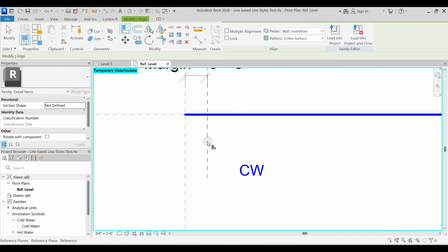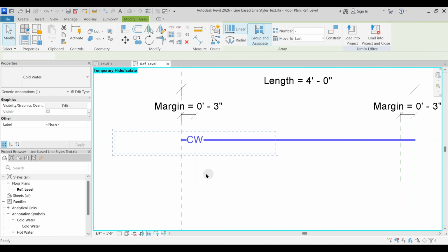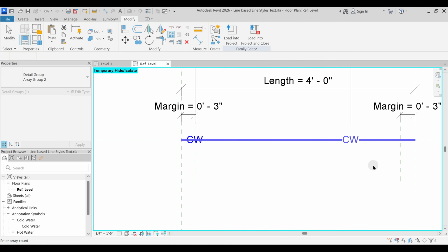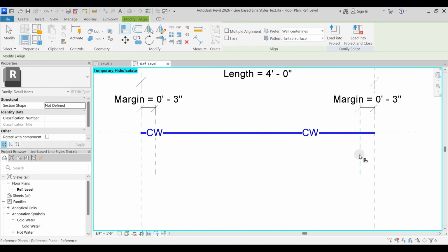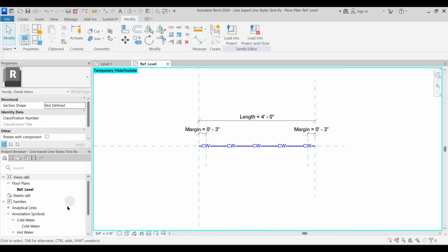Now use that same process, lock and lock. Okay. Select this and create an array of this from here to here. And just say that align, lock, and press tab and select this reference plane center front back and this reference plane associated with that text. Then select this and change this equals to number. That's fine. Clear?